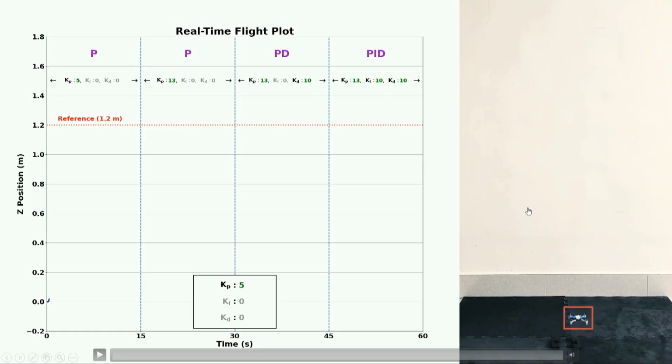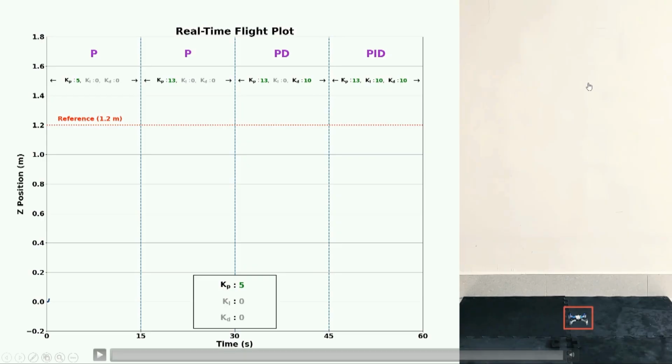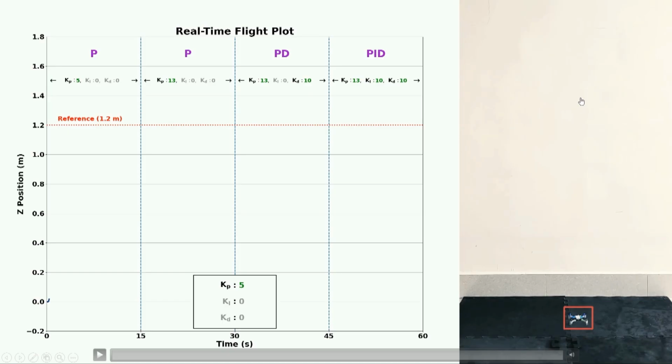One thing that you need to remember is that the drone does not have just one PID controller. It actually has a lot of PID controllers, because there are 3 directions. I am just concentrating on the PID controller that takes care of the altitude. When we talk about drones in detail, you will see that there are almost 6 to 12 PID controllers present in the drone. But here I have fixed all the PID controllers except the one that is changing the altitude, and for that controller, I am changing the values of P, D and I to show you the effect on the altitude of the drone.